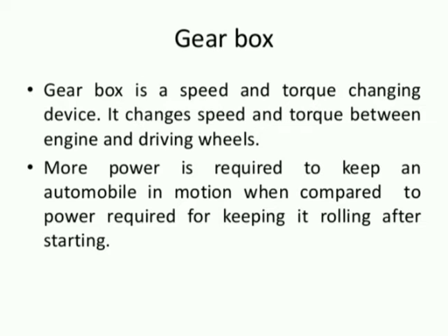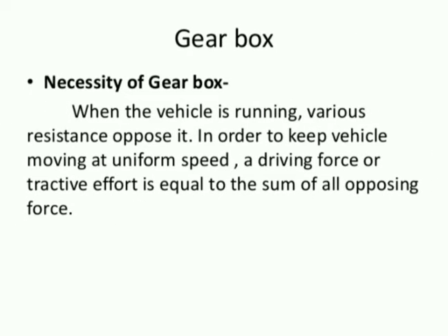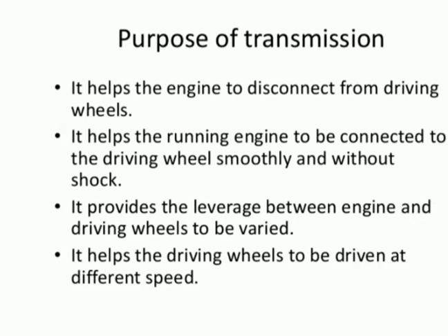More power is required to keep an automobile in motion when compared to the power required for keeping it rolling after starting. And the necessity of gearbox is when the vehicle is running, various resistances oppose it. In order to keep the vehicle moving at uniform speed, the driving force or tractive effort must equal the sum of the opposing forces.